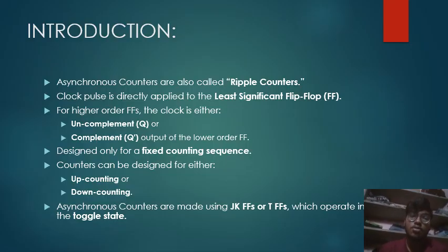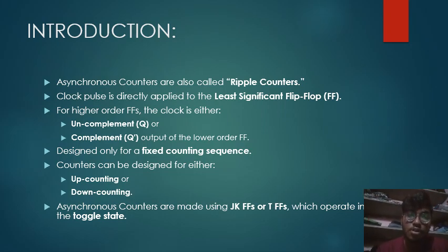In these asynchronous counters, the clock pulse is directly applied to the least significant flip-flop. The clock pulse or control input is applied to the LSB flip-flop. For the higher order flip-flops, the clock is the output of the previous flip-flop, either the complemented or uncomplemented output. In these asynchronous counters, only fixed counting sequences are used.